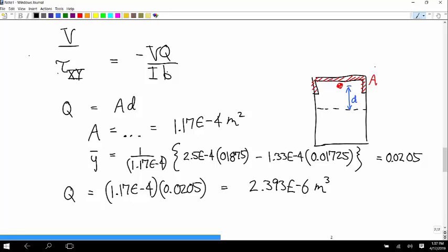Do you have a feel for what that B is doing in there? What that B is doing is telling you how much material you have keeping this thing from breaking apart at that point, from shearing apart at that point. And so it's not just the thickness of that wall that's keeping it from happening. It's the thickness of this plus the thickness of that. Well, no. It's not going to be this 0.02. It's going to be 6 millimeters. You know what I mean? Oh, I see, the whole thickness. Right. That's right.